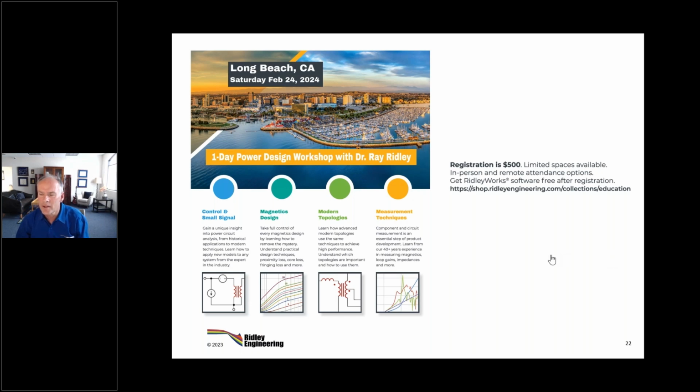Have I measured the winding without the core? Yes. Is the AC closer to DC? Yes. Does it mean anything? Just that it's the core gap that's causing it. We've also done it with cores without gap, for transformers, with the core loss present or not present. There's not much difference. It's only bad in this case because the gap is in the wrong place, quite honestly.